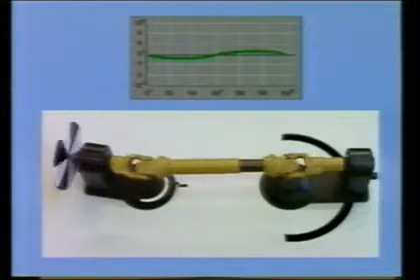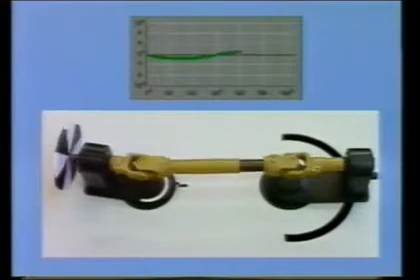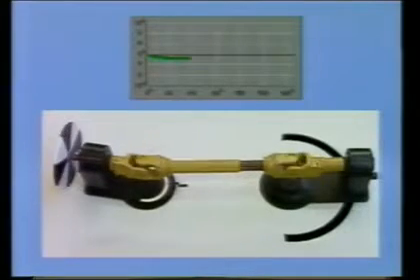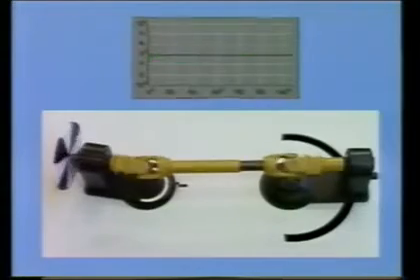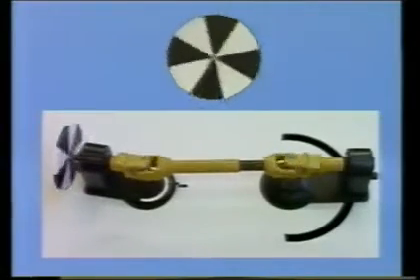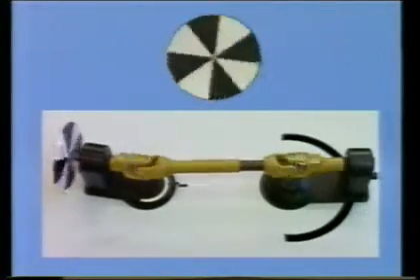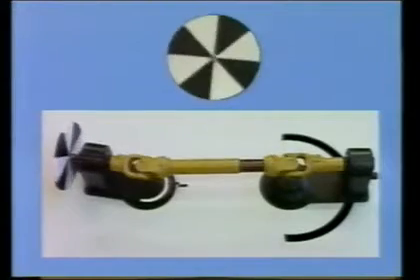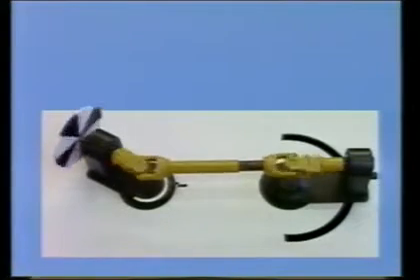At a working angle of 30 degrees, as seen here, the velocity variation of the rotary motion is already 30%. Lead and lag angles of the driven joint are clearly recognizable as oscillations in the graph. The non-uniform rotary motion can now also easily be seen on the black and white disc. Premature wear of drive components can be expected.